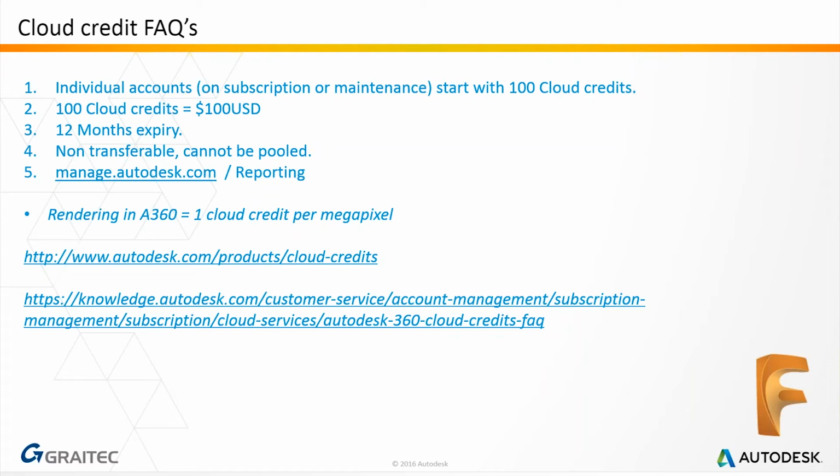One last thing I'd like to do, I'm just going to come up here to manage, and I'm just going to set the mesh a little finer. So I'm going to up the mesh density here to the tightest possible. This is a pretty small part, so I know I can put a fairly tight mesh on there, and it's going to be okay. It will warn me that's going to take a bit longer. I'm all set. I'm ready for the optimization. So I'm going to come up here and click solve.